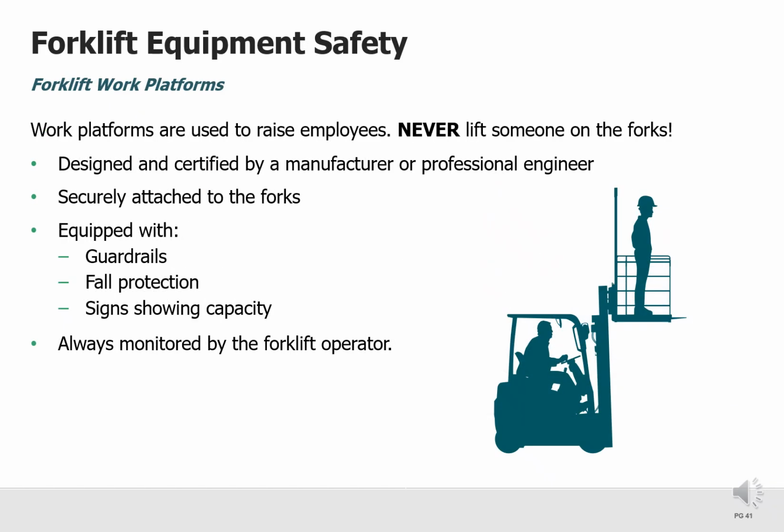Work platforms are used to safely raise employees, but never lift someone directly on the forks. Only use platforms that are designed and certified by the manufacturer or a qualified engineer. Make sure the platform is securely attached to the forks before use. It must include proper guardrails, fall protection, and clearly marked capacity limits. And remember, anyone on a work platform must be continuously monitored by the forklift operator.